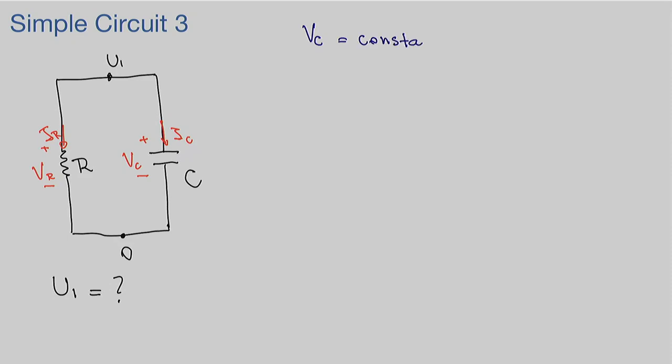Okay. So if the voltage across the capacitor is constant, that simplifies our lives a little bit. Why? When we look at such a circuit, because if I write the current element's definition for the capacitor, it is going to be capacitance times dV/dt, where V here is the voltage across the capacitor, and we are analyzing circuits considering steady state.